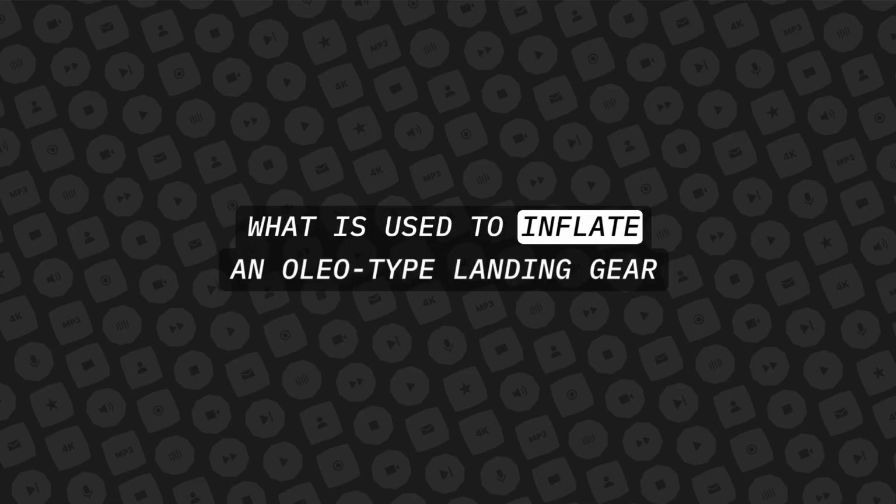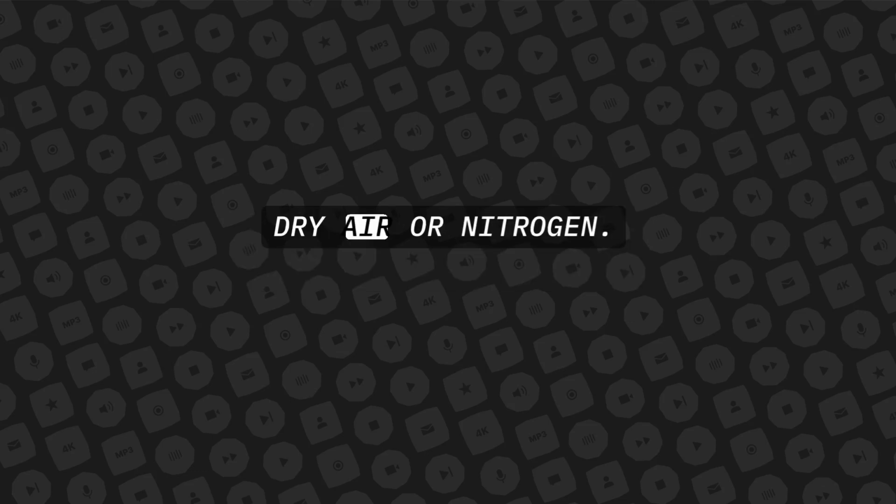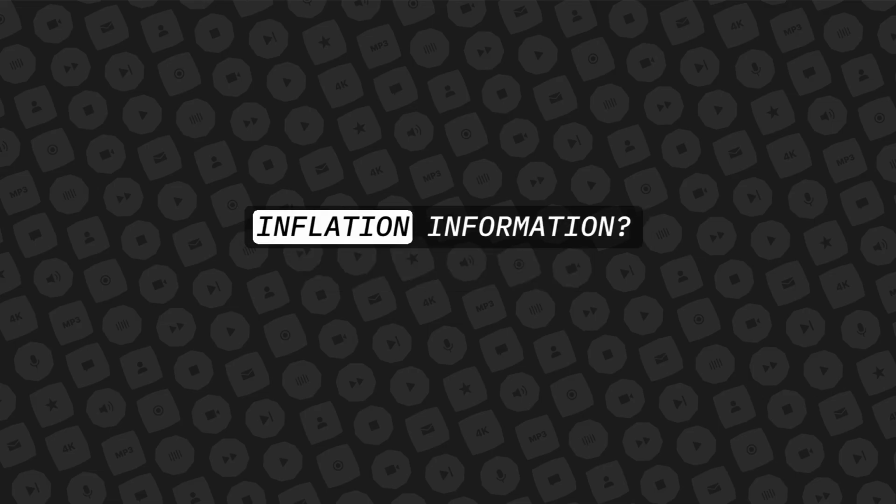What is used to inflate an oleo-type landing gear shock strut? Inflate the strut with high-pressure source of dry air or nitrogen. Where would you look to find proper tire inflation information?